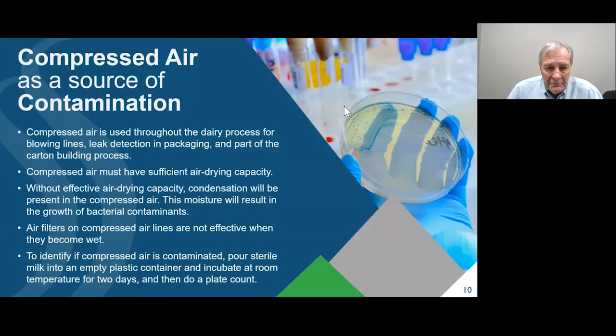Compressed air, I want to say a little bit about compressed air. Compressed air is usually something pretty much overlooked by the dairy processor. Compressed air is normally not a problem if it's kept dry. However, air dryers are used in dairy plants. Oftentimes these air dryers are overused, lose efficiency, and do not remove all the moisture, creating condensation. The condensation then becomes a source of contamination. One of the things that the dairy people will argue with, say there's filters in the air lines that are supposed to remove the bacteria. What I have found is if filters get wet, they actually grow bacteria, become a source of contamination.